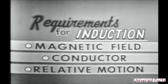That's right. So we know from that, then, that the rotor cannot turn as fast as the magnetic field, because if they were both turning at the same speed, there would be no relative motion between them. No relative motion, no induction. No induction, no current flow in the rotor. And, of course, if we didn't have current flow in the rotor, there would be no magnetic field, no magnetism in the rotor. The rotor would just be another chunk of iron.